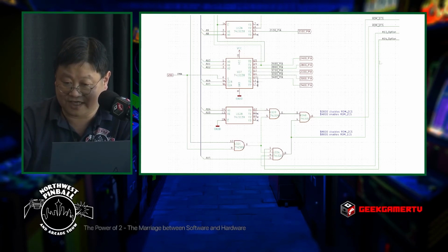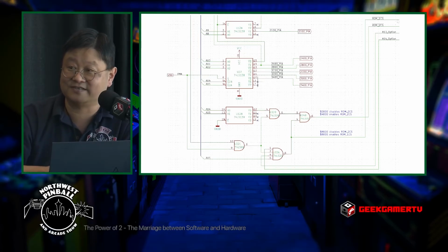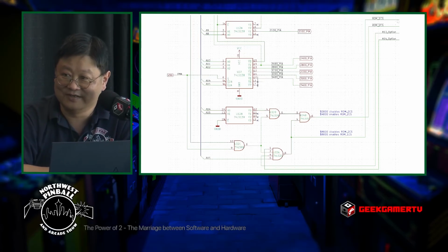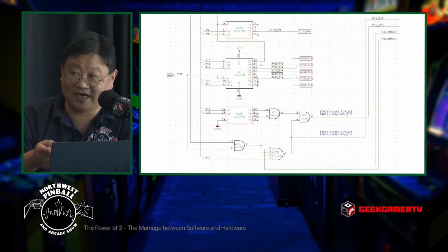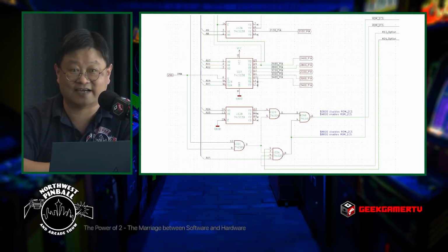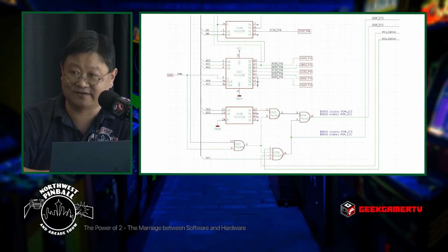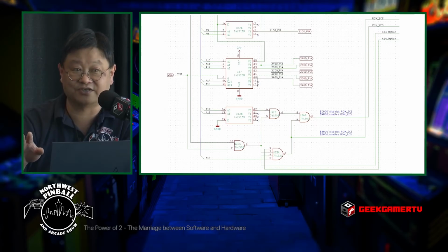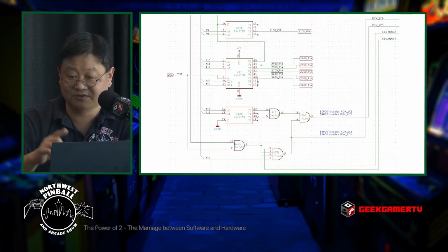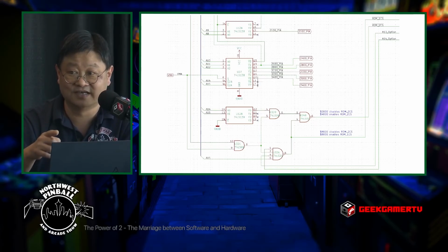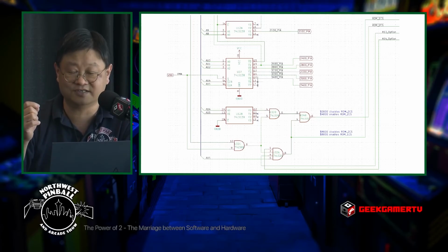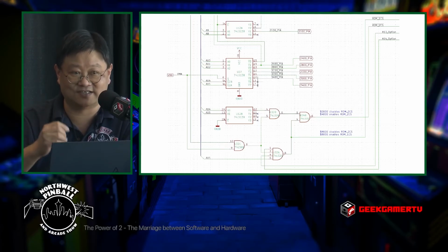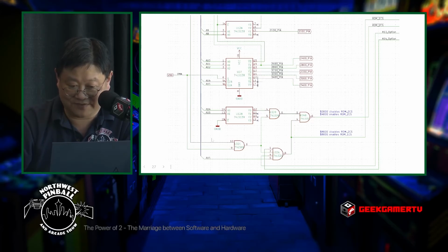That signal goes up to ROM1CS, U27. And the chip select signal for the ROM is active low, which is why that output 0 activates that ROM chip. The bus says A15 is 1. As soon as that happens, this decode logic goes through, produces a 0, low output on ROM1CS. The ROM chip wakes up and it says, oh, you got something for me. And it starts dealing with it. And you can see the same thing here with 14 and 15.